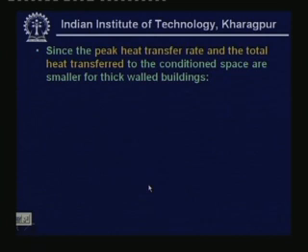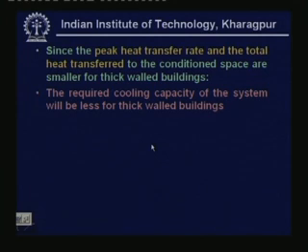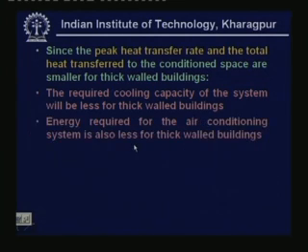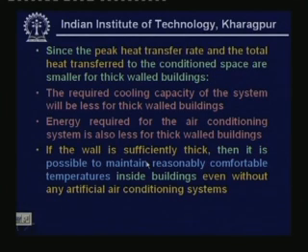Since the peak heat transfer rate and the total heat transfer to the conditioned space are smaller for thick walled buildings, the required cooling capacity of the system will be less for thick walled buildings, so it is an advantage. And energy required for the air conditioning system is also less for thick walled buildings. So this is also an advantage. And you will find that if the wall is sufficiently thick, then it is possible to maintain reasonably comfortable temperatures inside buildings even without any artificial air conditioning systems, because of the small decrement factor and large time lag.